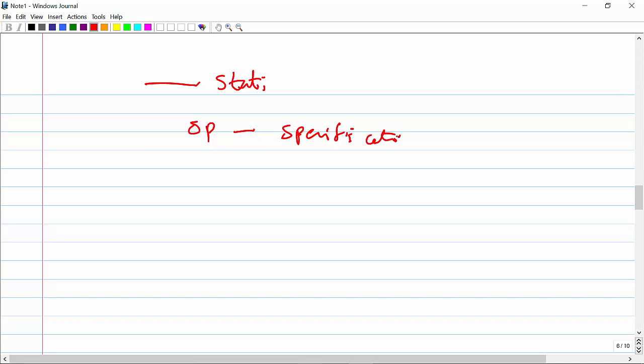For that, you can give the specification to the Monte Carlo simulation, and you can run 100 or 1000 runs. Among those runs, across all these combinations of process and mismatch, if the system works perfectly, you will get 1000 out of 1000.